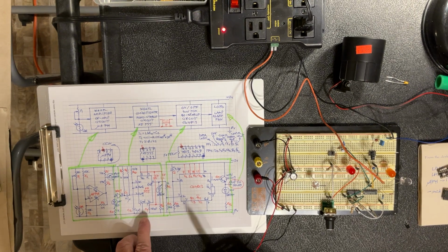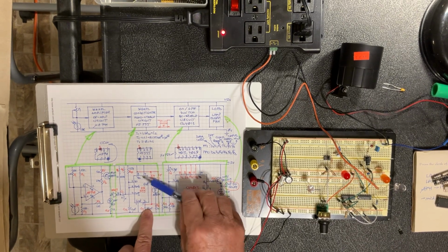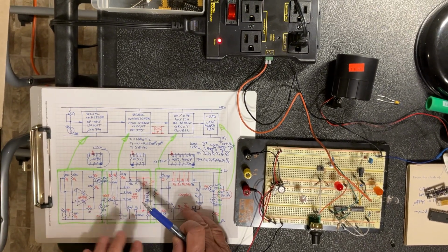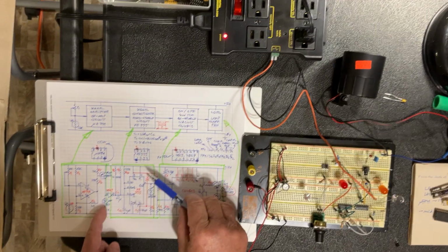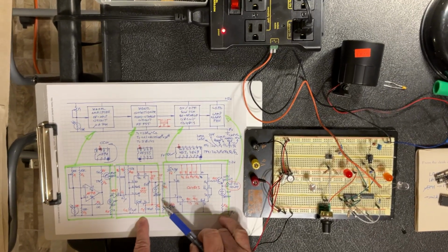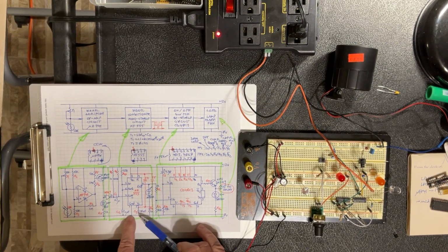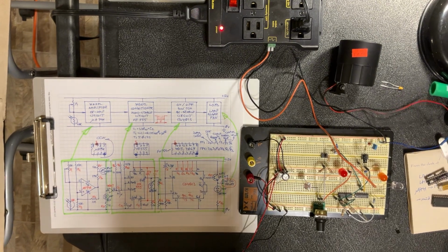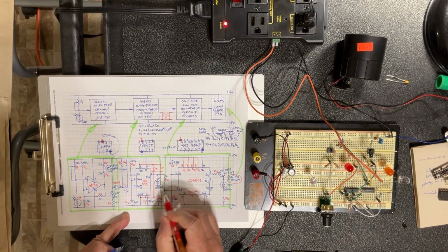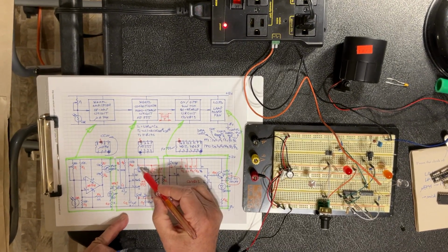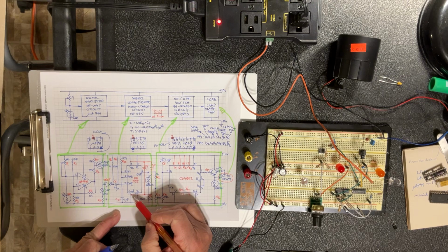Good. One other thing I should have said before going to the flip-flop is that anytime you use the 555, the 555 has a little drawback. Through the power lines, it can propagate some unwanted signals, and you want these signals to be reduced to a minimum. This is why it's a good practice that right here on the package, you place two capacitors between pins 8 and 1. Why? Because on that particular package, pin 8 is the positive voltage and pin 1 is the ground.